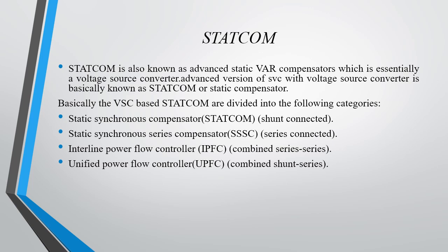Then what is STATCOM? STATCOM is also known as an advanced static var compensator, which is essentially a voltage source converter. The advanced version of SVC with a voltage source converter is basically known as STATCOM, or static compensator.